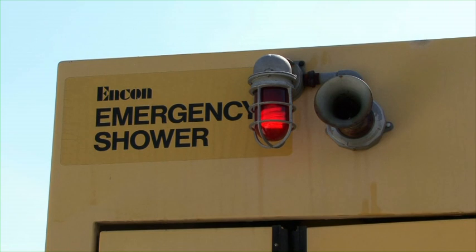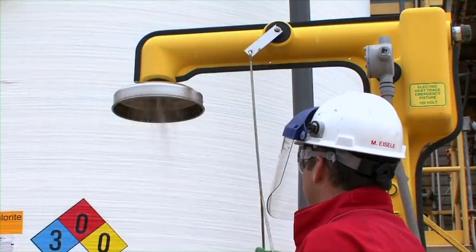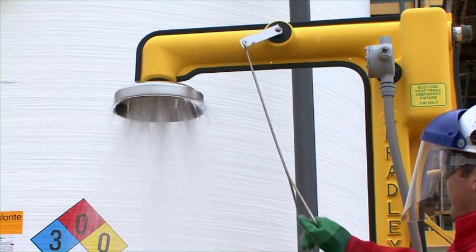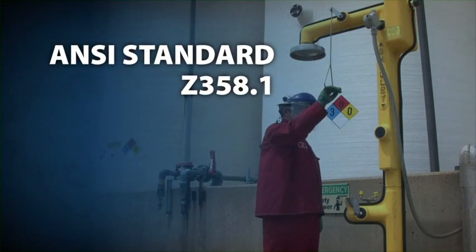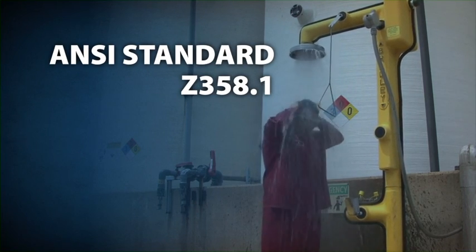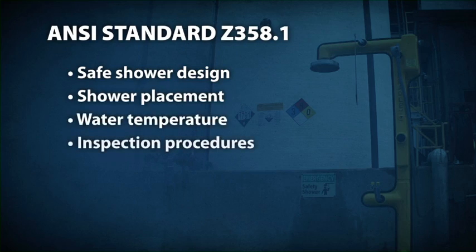Consideration should be given to providing alarms on safety shower handles to automatically alert other personnel to the emergency. Eye wash fountains and safety showers should be checked regularly for proper operation, including water flow and temperature. Safety showers and eye wash stations should be designed and provided in accordance with OSHA regulations. Users should also consult the latest ANSI standard Z358.1, which outlines additional criteria in the safe use of safety showers. Topics covered include safe design, placement, water temperature, and inspection procedures.